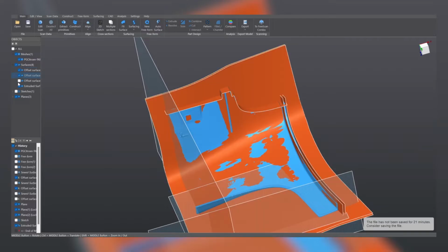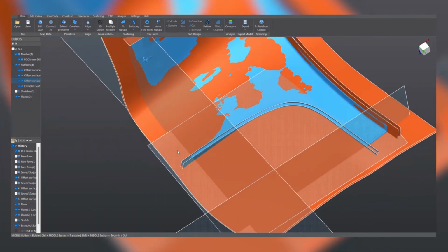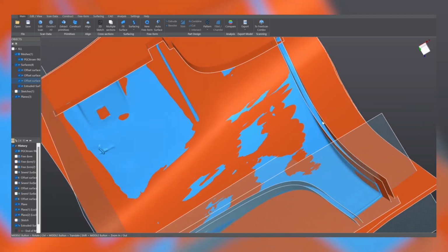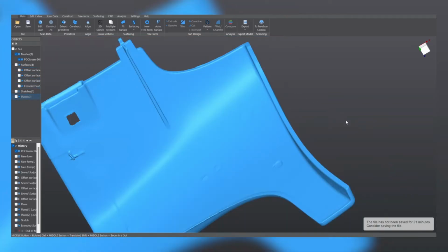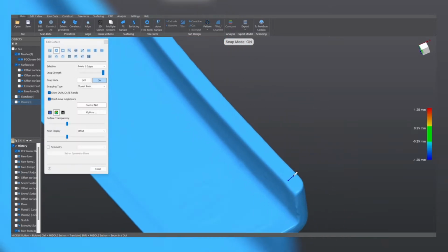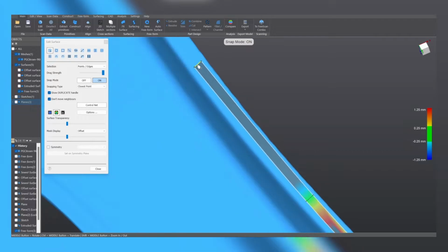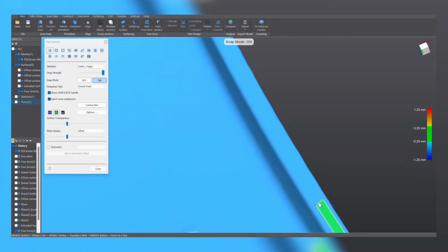And let's see what's left. So our surfaces will close here. They will close here, here as well. Oh, we need to reproduce this shape here, this face here, to close these 2 surfaces. And this we are going to do with a freeform. So again, let's hide everything, also the planes. And you know the process. We create quickly a new face here, update the view, and extend it. Always snapping on the mesh.